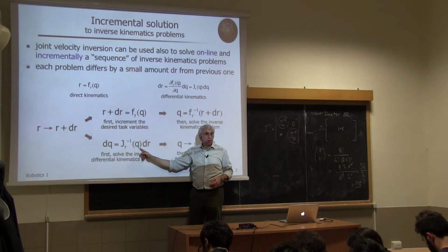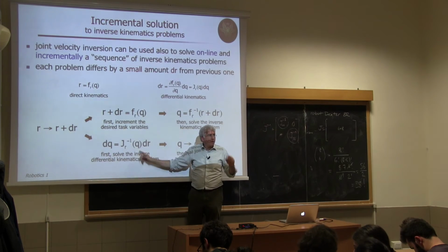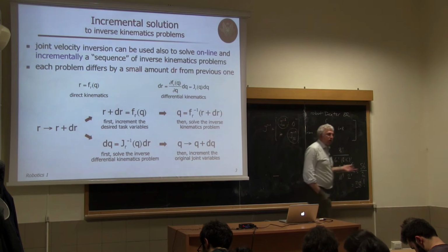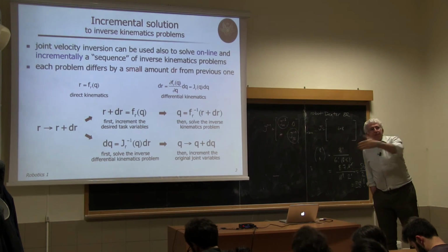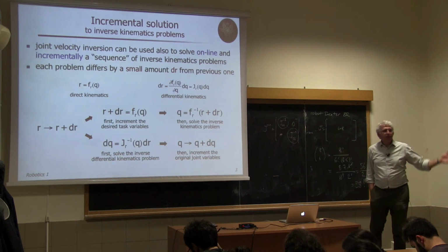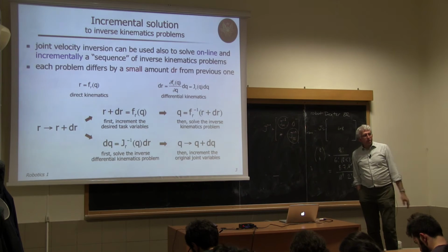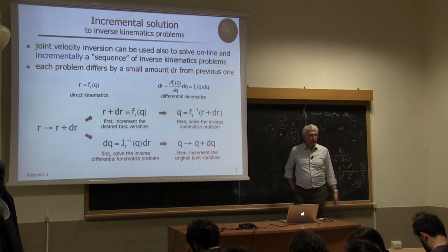Doing this is in fact applying Newton methods for solving the next inverse kinematic problem in a numerical way. We have seen it now from a different perspective, just thinking about differential inversion of the kinematic map, so using Jacobians at the velocity level. But it's exactly the same thing.